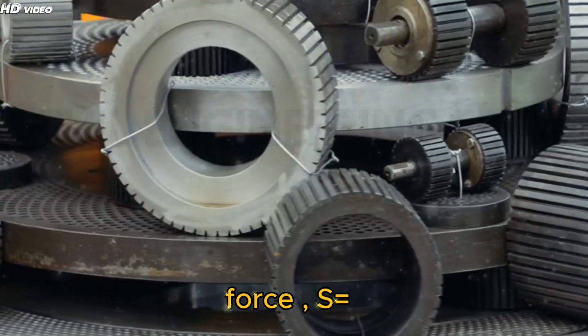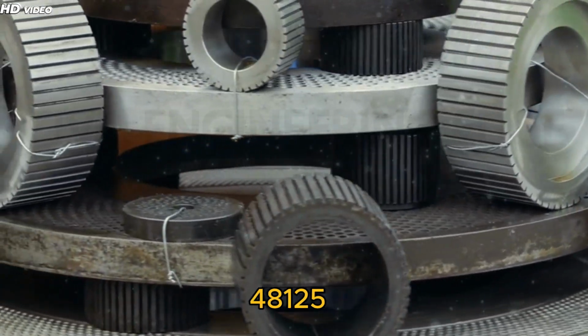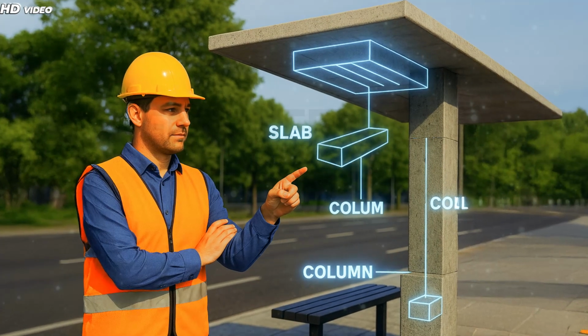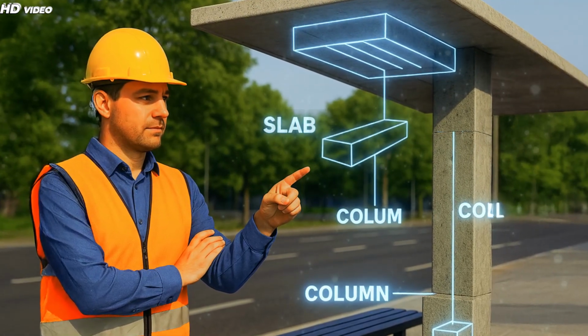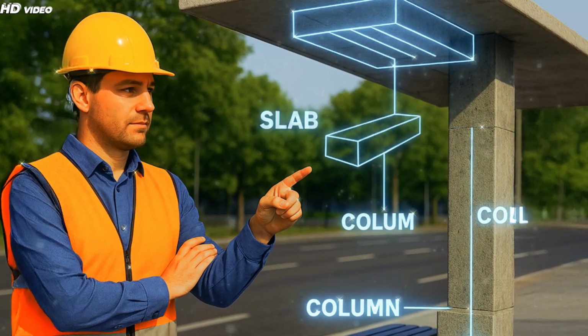Maximum shear force, S equals 13,750 x 3.50 equals 48,125 Newton. Nominal shear stress tau v equals S over b d equals 48,125 over 300 by 667 equals 0.24 Newton per millimeter squared.